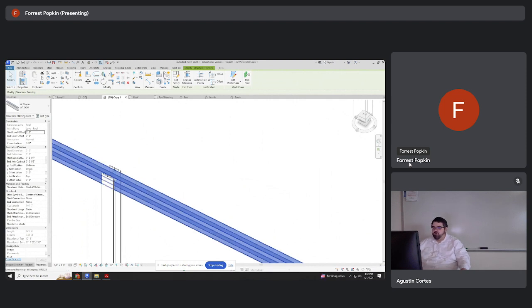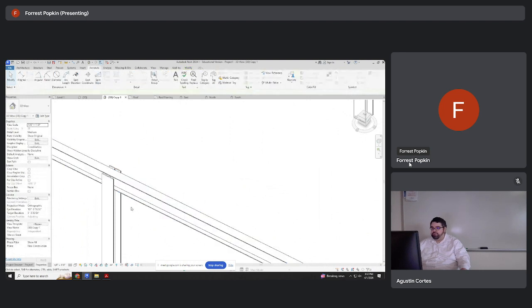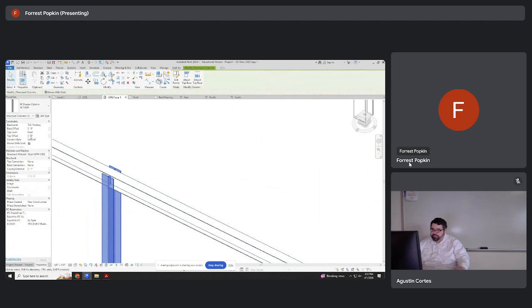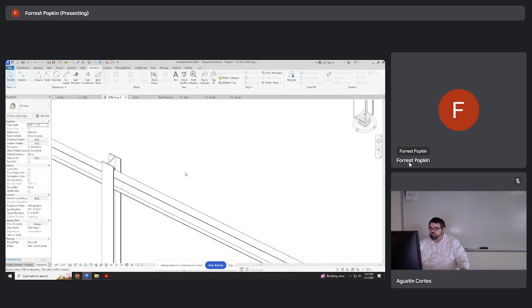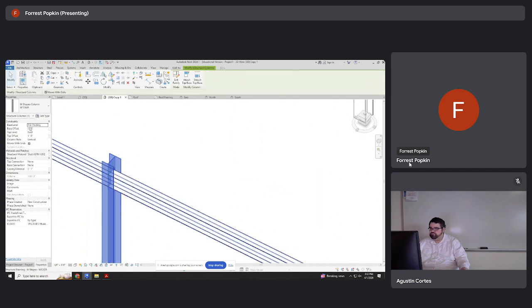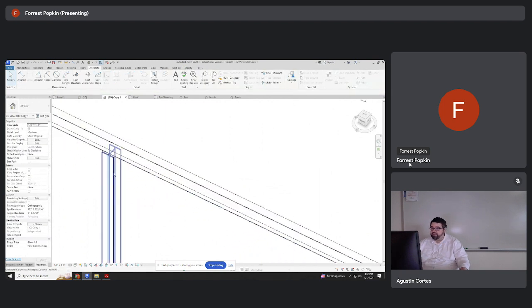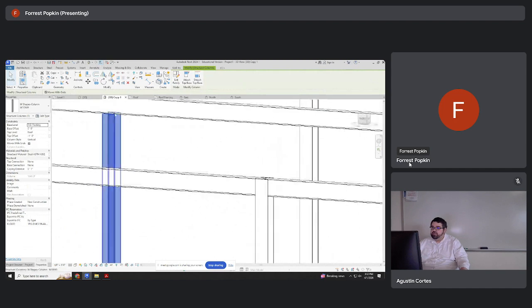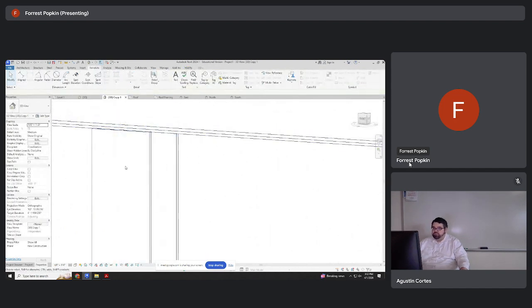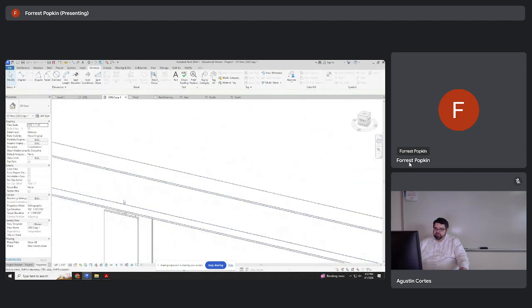So it's a depth of 12 from flange to flange nominally, meaning that if I were to offset this guy by a top offset of negative 12, whoops, it went up, negative 12, it will crop it to approximately where it needs to be. So if that's how I was going to detail it, that's what it would be.